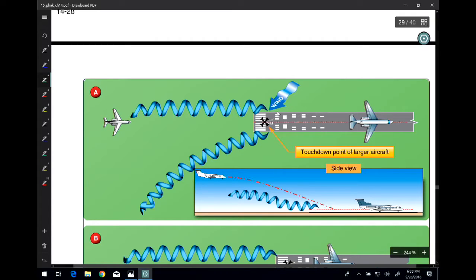The other thing you have to be concerned with is the wind, and here's why. You may think, okay, I'm okay with the vortices because I'm above them. Well, let's say that this wind right here is showing a left quartering headwind. That kind of pushes the vortices this way and gets them out of your way when you're coming in to land.